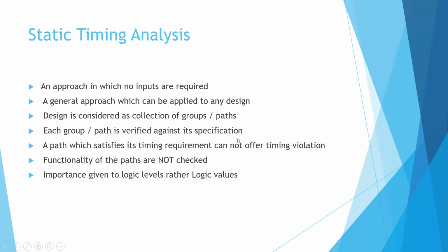Next comes the static timing analysis. Static timing analysis is a very popular method of timing analysis in VLSI, and it is an approach in which no inputs are required. Here we don't give any input vectors. It is a general approach which can be applied to any design irrespective of the criteria. We can use any design for the static timing analysis.